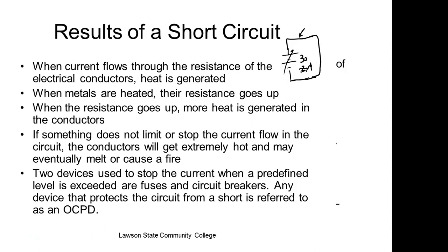It's got that cheap plastic insulation on it. What happens when they get hot? It melts off. So as it melts off, what happens? Then your source comes in contact with your return. The dang thing has enough resistance to prevent from blowing your breaker, but now it gets red hot. And what does it do now? Catches on fire. So, guys, your outlet should never get hot. If you got an outlet that's getting hot, it means you need to replace that thing or get somebody to come in there and replace it, because the hotter your copper gets, the more it oxidizes. The more it oxidizes, the more resistance it gets. Now you get down the line, you plug something in, and it's trying to pull it through that R.